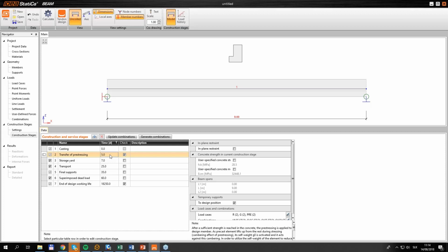Or the prefabricator manufacturers, they know how to speed up the process, so they can use a specified concrete strength at this stage. So if I include like 30 megapascals, you can see that the time is calculated accordingly, and by this you can always do the analysis also for the members which are younger than 3 days, because you ensure this value based on the tests.